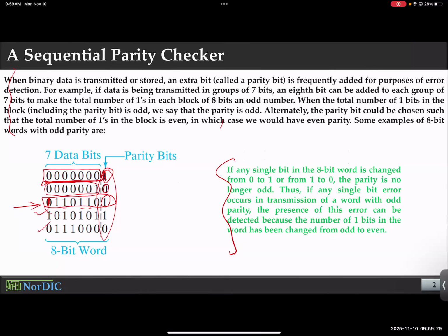But if you decide that every 4 bits I'll have a parity, then every time you encounter a mismatch in parity, you have to clear those 4 bits, which is good. You don't have to discard a lot of data. But it is bad because you're wasting a lot of parity bits. If you have 10 bits, 2 of them will be parity. So you have a useful 8 bits. You see my point here, right?